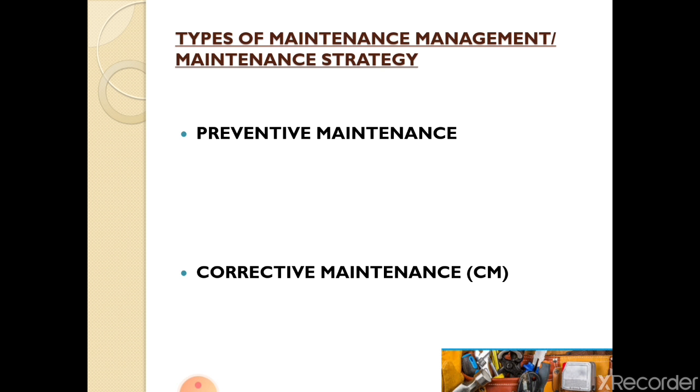So what are the differences between preventive maintenance and corrective maintenance? Preventive maintenance is a proactive approach, and corrective maintenance is a reactive approach. Preventive maintenance is done on a routine basis, with regular inspection taking place. But in corrective maintenance or breakdown maintenance, it is remedial and non-routine. When the repair or breakdown happens, at that time the repairs and inspection follow.